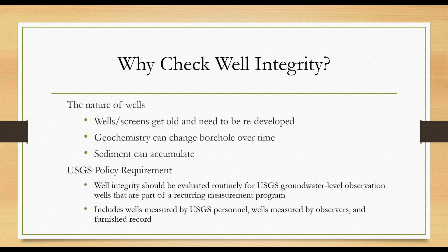As I mentioned, we have a policy that says well integrity should be evaluated routinely for USGS groundwater level observation wells that are part of a recurring measurement program. This includes wells where we accept the data, which we call furnished record.